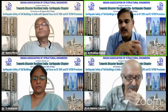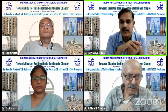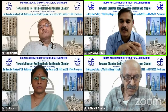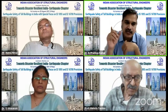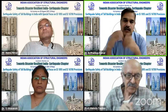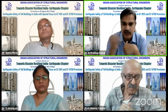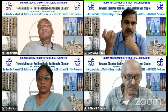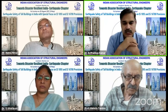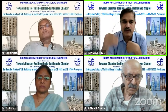what code is recommending. All the tall buildings over 150 meters height, if they are instrumented, we will get the real data, ambient vibration data as well as real earthquake data. For ambient vibration data, we need high sensitivity equipment so that we collect ambient vibration data. And real data, when strong ground motion, that means when a real earthquake occurs, what is the natural period with which the building was vibrating? So those 2 things will make our database rich,